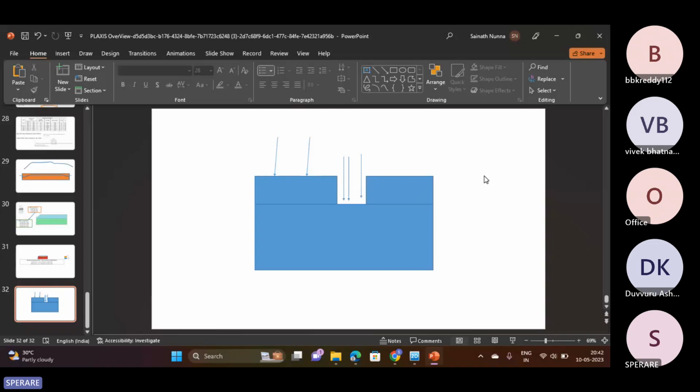What happened to your borehole conditions when you captured the soil in the initial conditions, for the sampling before the excavation? Before the excavation, you captured the soil, sent it to the lab, and got the material properties of the soil. After the excavation, when your site is exposed to environmental changes, if you are still using the old material properties, which are not so relevant, that is not good at all.